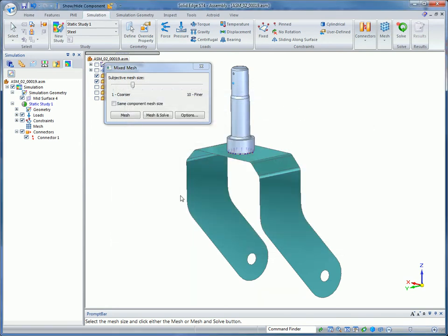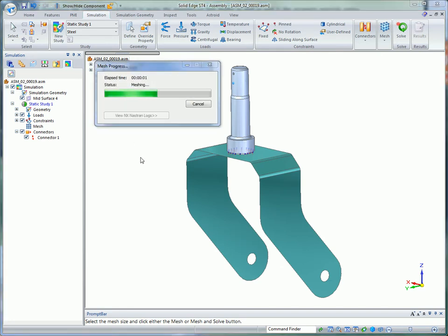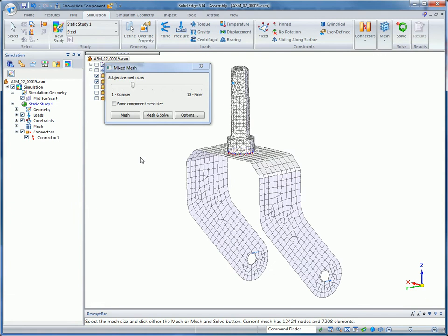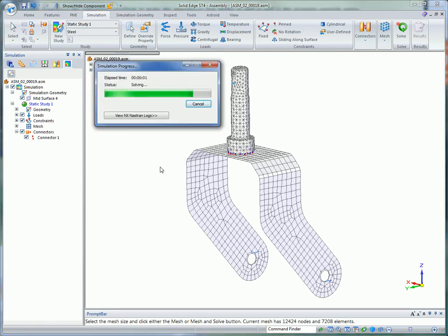To optimize complex models, a maximum angle tolerance limits the angle between facets on curved surfaces, while curvature-based options automatically increase mesh refinement on tightly curved faces to help ensure higher accuracy without sacrificing overall solve performance. Also, quad edge layers forces placement of quadrilateral elements around stress risers such as holes. This new feature is yet another way SolidEdge Simulation helps optimize solve speed and accuracy.